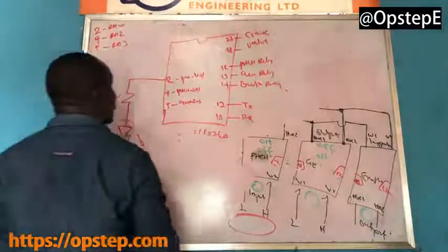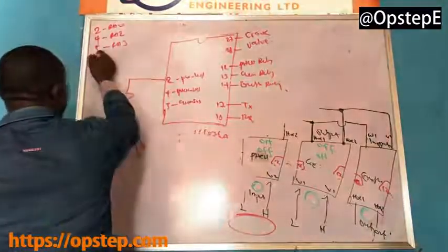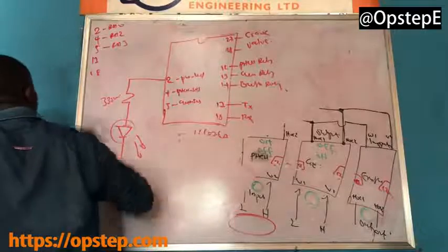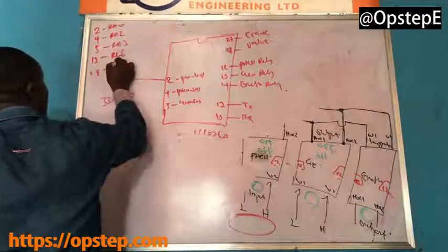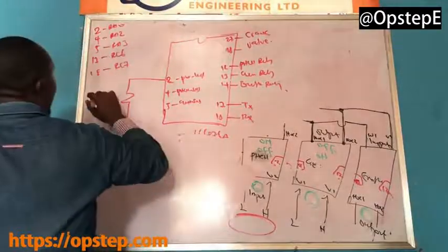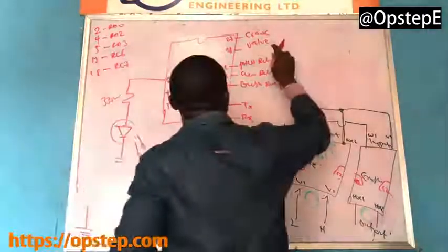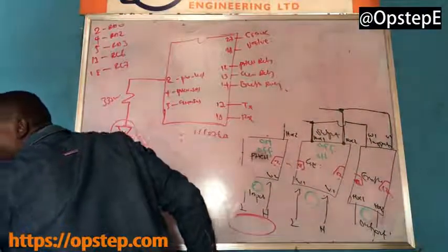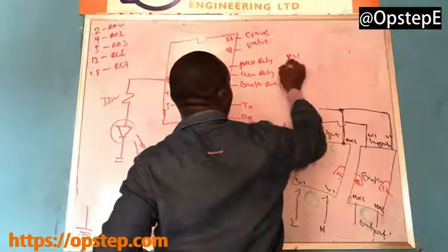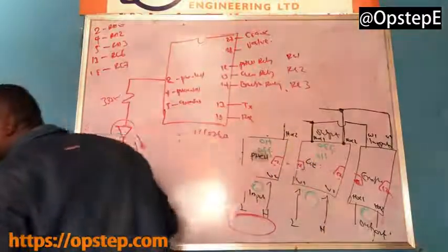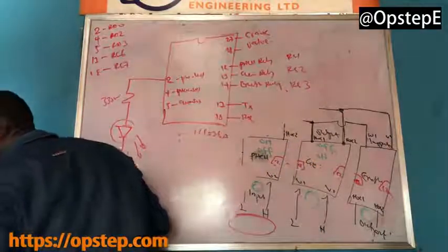Well done. Your pin 17 and 18 is RC6 and RC7, I'm just going to explain all of that. Your pins 12, 13, 14 are RC1, RC2, and RC3. Your 27, 28 are going to be your RB6 and RB7.